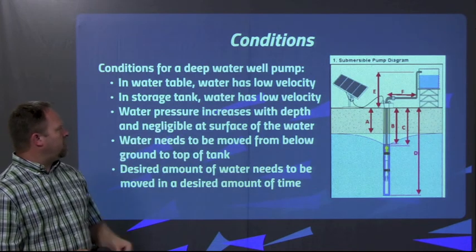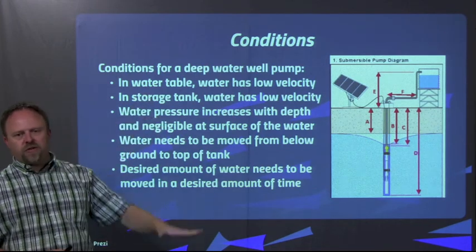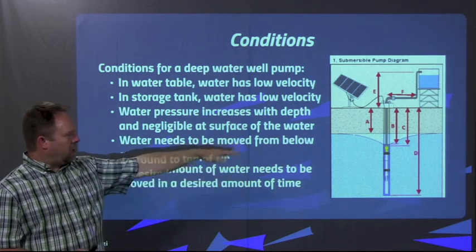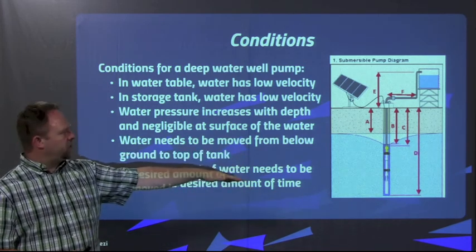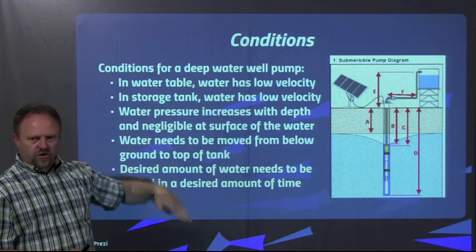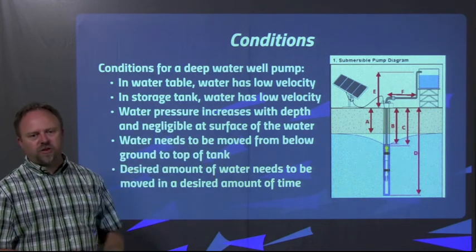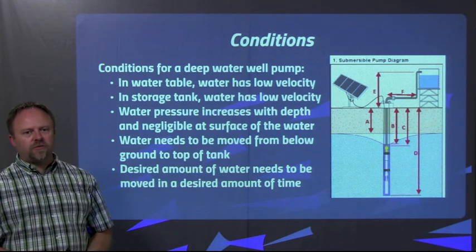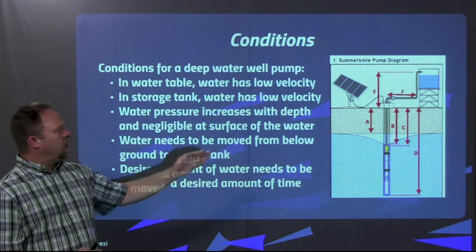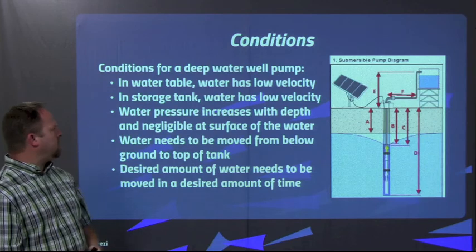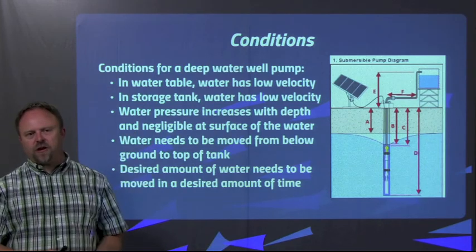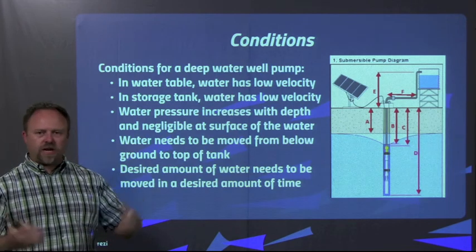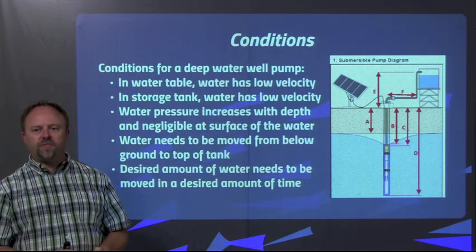We also are going to be looking at the water pressure. As you go down underwater, the pressure increases. So if you're under the water table a little distance, not looking at how far underground you are, but how far below the surface of the water table are you, there will be a little bit of pressure that the pump will see at the intake. At the exit, we're pretty sure if we have our pump exit at the top of the tank, we really don't have any pressure besides the air pressure, which will be considered negligible.